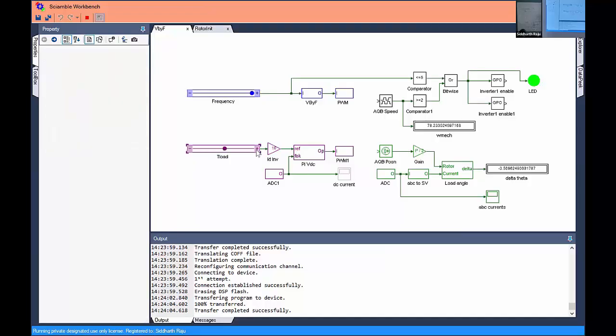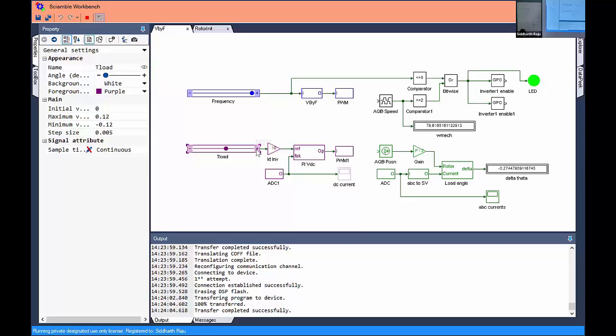Now I'm going to start adding the load torque. Right? So let's keep adding. As I keep adding, you should see that the delta theta, that term, starts to increase. Right? But basically saying that the rotor is falling behind the stator. What speed is the rotor rotating? Is it at the same speed as the stator? Hannah, you're saying no, why not? At steady state, they have to be the same, right?